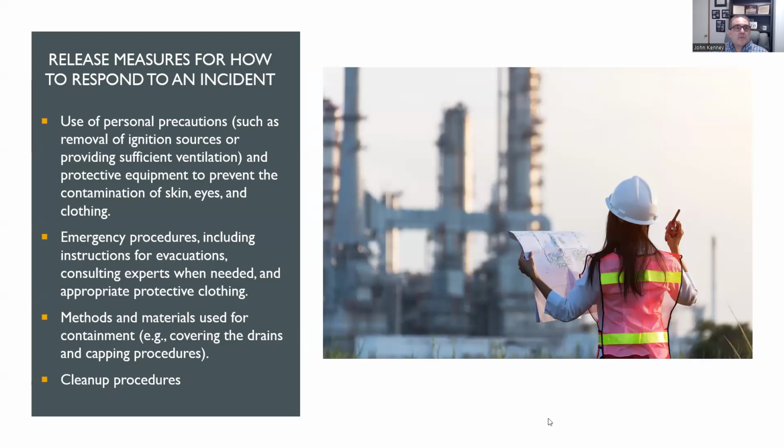Release measures for how to respond to an incident. Use of personal precautions such as removal of ignition sources or providing sufficient ventilation, and protective equipment to prevent contamination of skin, eyes, and clothing. Emergency procedures, which include instructions for evacuations, consulting experts when needed, or appropriate protective clothing.